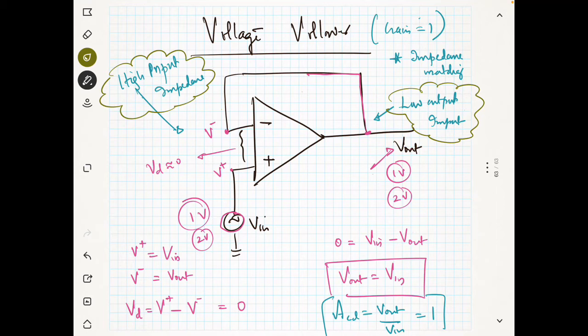I think you know the advantage of high input impedance and low output impedance. If you want to connect a small sensor which is producing a voltage of the order of millivolts, you can first connect the voltage follower. After that you can connect whatever circuit you like. It will not change the voltage output from the sensor, but it will capture everything. But if you connect some other circuit directly, it cannot capture the complete voltage. There will be some loss because of the impedance mismatch, resistance mismatch. So that is the advantage of the voltage follower here.